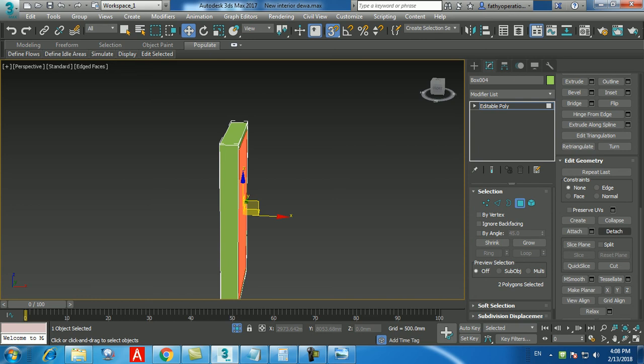After making the 70 mm insert, select the front polygon, the outside, and extrude it minus 150. To check it, unisolate quickly. Click the light bulb, then click the light bulb again to isolate. Done? Outside. Okay. Extrude minus 150.